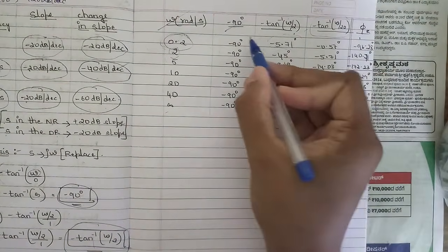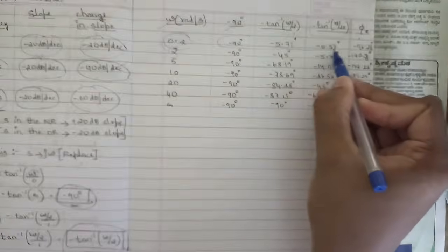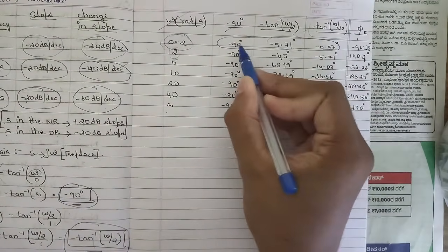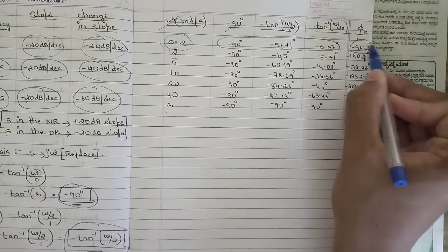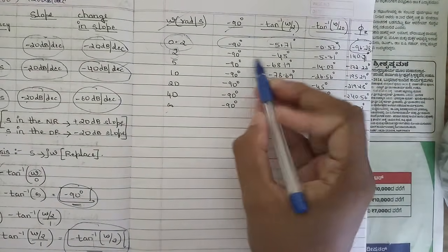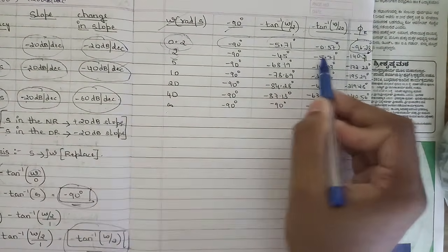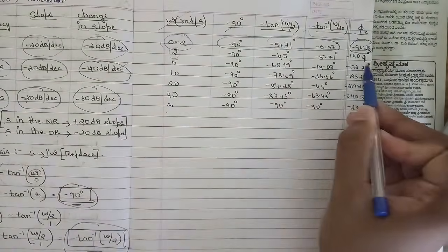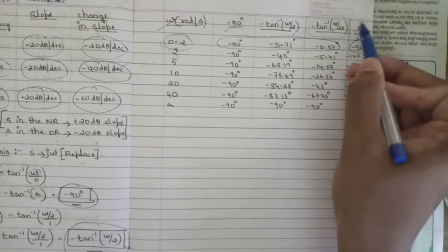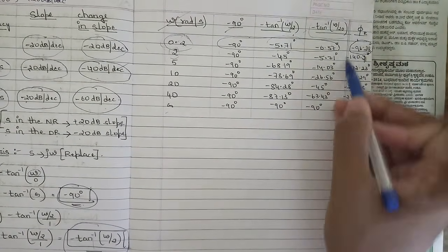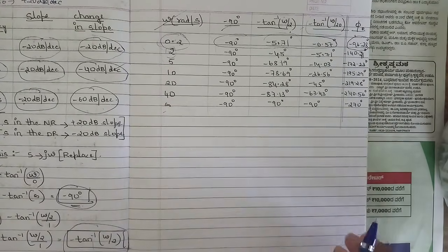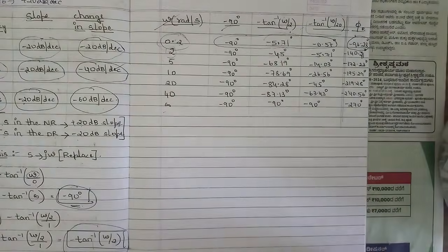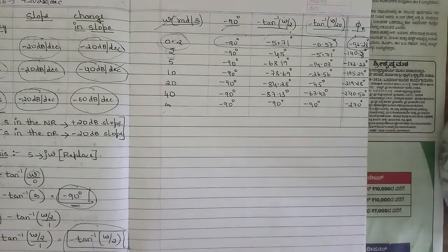Then what we should be doing is adding all these three angles. Okay, in the first row, whatever angles we have got, add all of them and write it in the final angle, the summation of all these three angles. Similarly, for the summation of these three angles, write it here, these three angles, write it here, and so on. Okay, this is the final table where we should be plotting these angles in the semi-log graph sheet. Okay, so these are some of the calculations which we should be doing. Now let's get to the graph part.